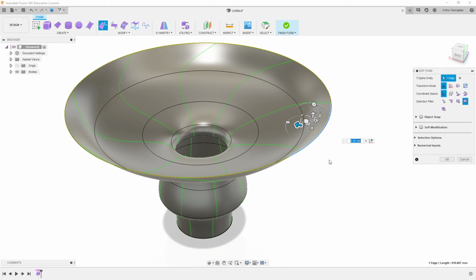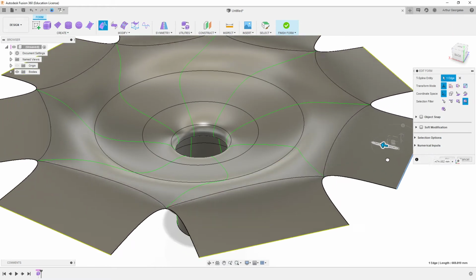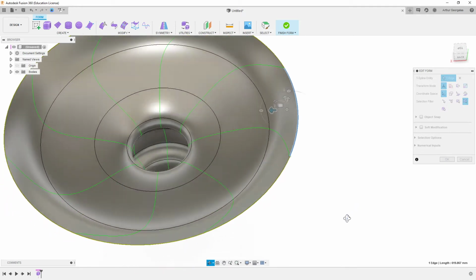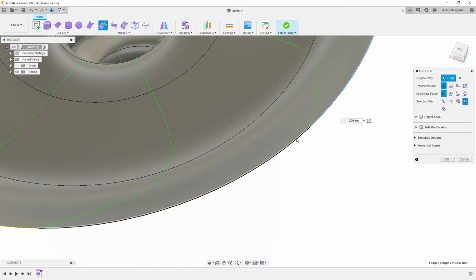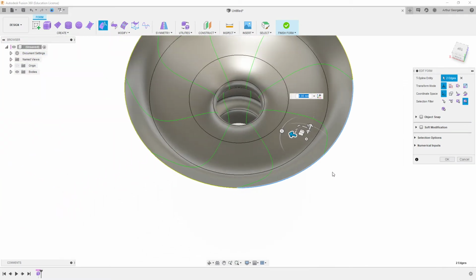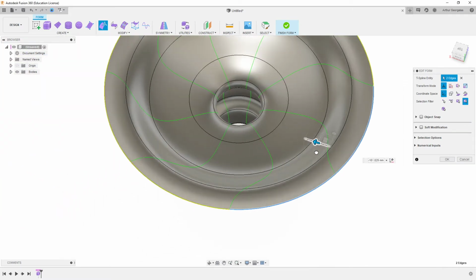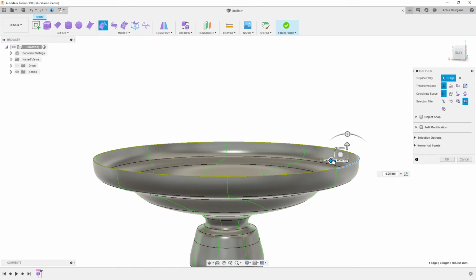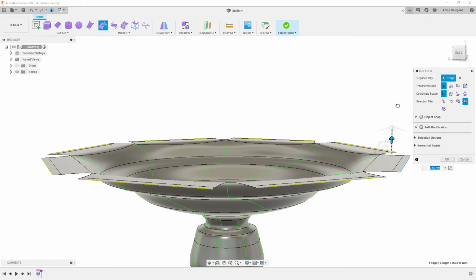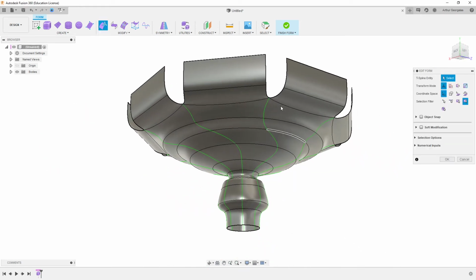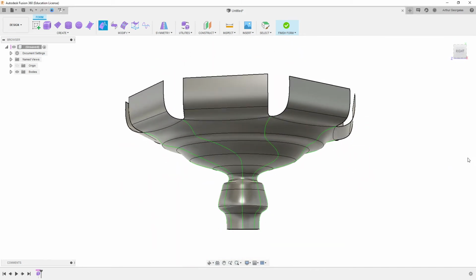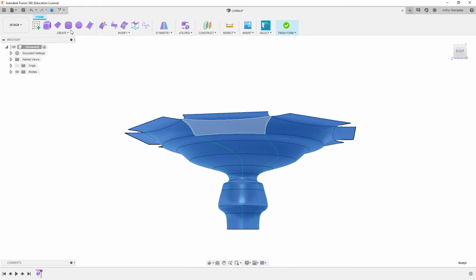One of the things to note is when you've got this turned on, if I extrude out by selecting that, it doesn't join them together. The way that anything with symmetry works is you need to select, even though it's got this highlighted yellow, the next edge over, and then it understands that it wants you to join them. So then when I pull it out, it joins all the rest of them together, as opposed to having one selected and then it just expands it out on its own like that, which sometimes you want to do, sometimes you don't. So yeah, that's kind of how you can play around with the cylindrical tool, or the cylinder, whatever it calls it.